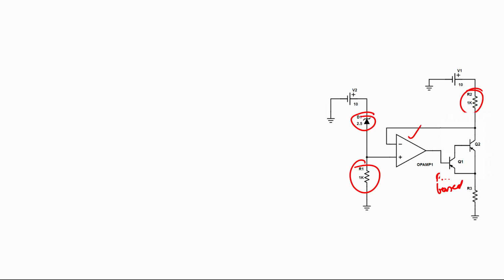In this case, if we are limiting to milliamps or 1 amp of current, we can go with a normal single transistor, or even smaller, a basic general purpose transistor. But when we are going with high current applications, a Darlington pair is a must, otherwise the transistor cannot withstand such a high current flowing through the circuit. Now, we will see the importance of the op amp, but before that, let us have a look at the use of having a Zener diode here, and the purpose of having this R1 resistor.